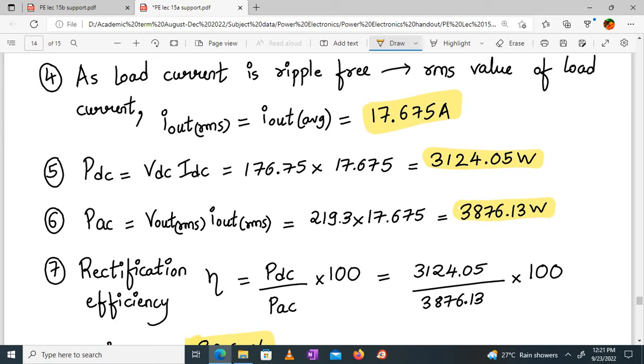अभी rectification efficiency का clue क्या दूँ? It should be less than 100%. अगर greater than 100% आ रहा है तो मतलब you are making a blunder. अगर बहुत कम आ रहा है, less than 50% or so, again you are making a blunder, because it's a semi converter, full wave bridge rectifier का efficiency you know ना, for diode it's greater than 50%.